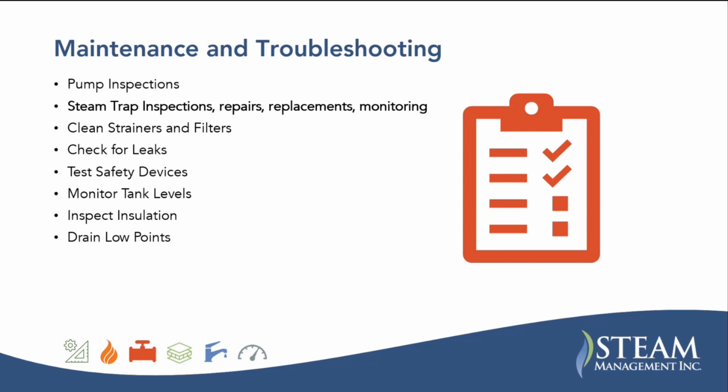And then, of course, keep your insulation in good repair and make sure that your condensate is properly being drained out of the steam system.